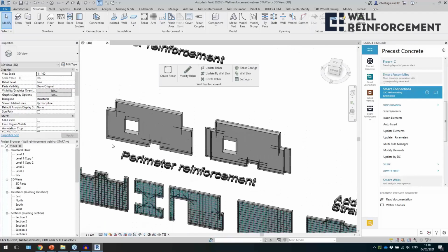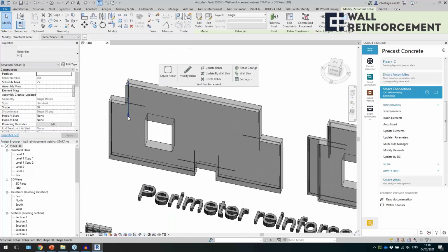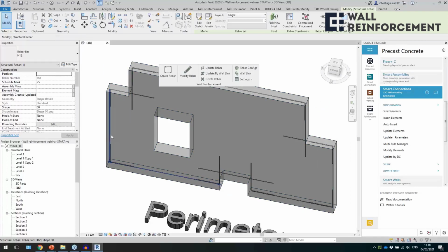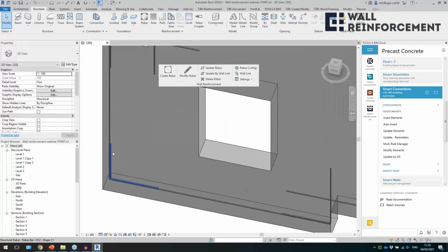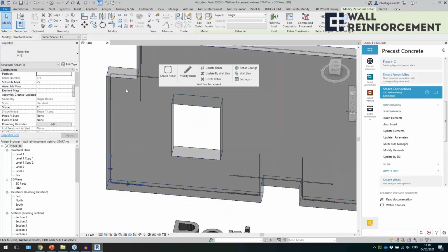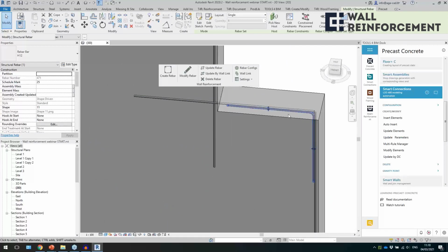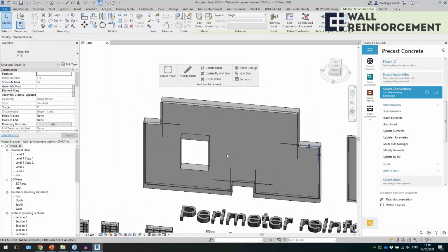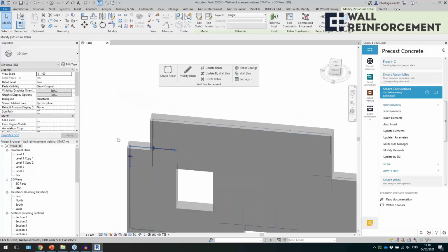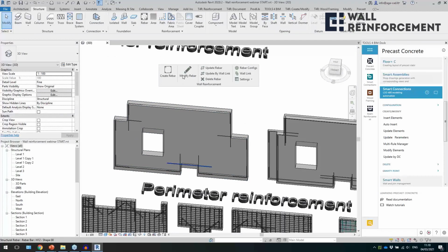Then we have the perimeter reinforcement option. So previously we had one of the options where, you see here, we have straight bars and then just an angle element in every corner. So we have these kinds of situations like this, or just placing maybe an L shape, depends on cutout size. But basically these settings look like this.